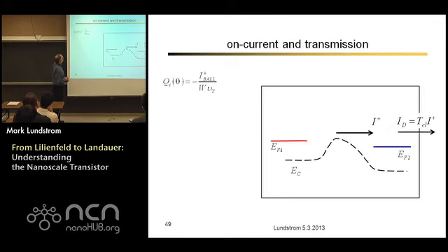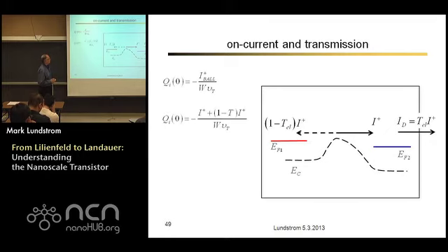The charge at the top of the barrier, current is charge times velocity. So if I want the charge, it's the ballistic current that's injected divided by the ballistic velocity. There's this width I have to worry about too. So that would be the amount of charge under ballistic conditions. When I'm not ballistic, then I have a stream. I have some carriers with positive velocities.